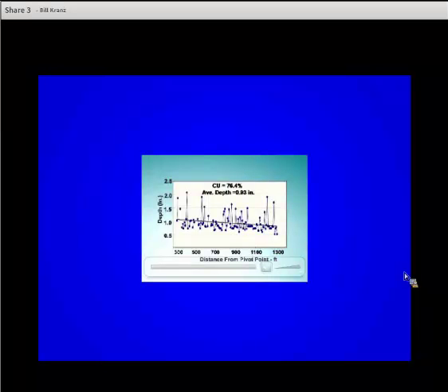And what happens then if you don't have uniform water application, typically, you'll see in this image coming up, is that areas that don't receive as much water as they should, if you take soil water readings in those areas, you're likely to compensate by irrigating again when you really shouldn't have to, just to get water into that portion of the profile.